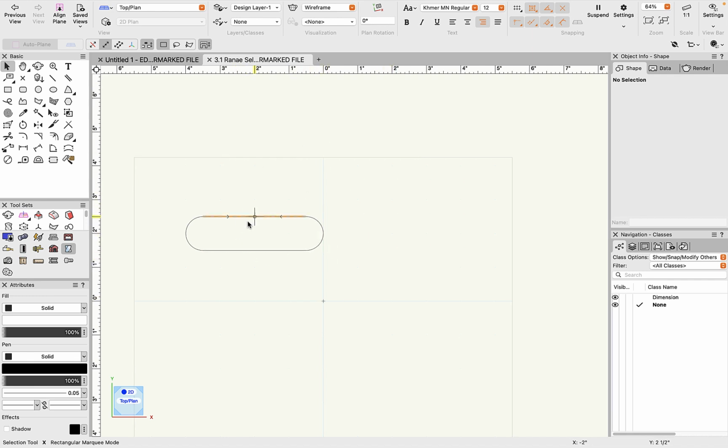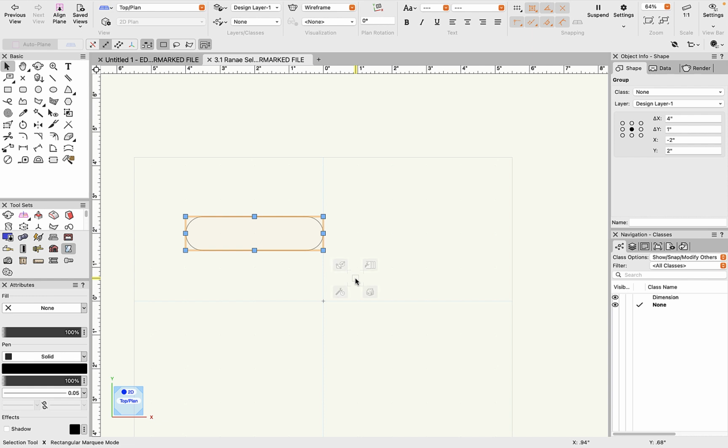Awesome. My placement now is sort of touching center, which I'm not too fond of. I would like it to be more up into that top left quadrant. So what I'm going to do is I'm going to select all 4 of those objects, and I'm going to group them together. The way I do that is Command G, and that has now made it one object. You can use Command U, which will ungroup them, but for now we're going to leave them together.